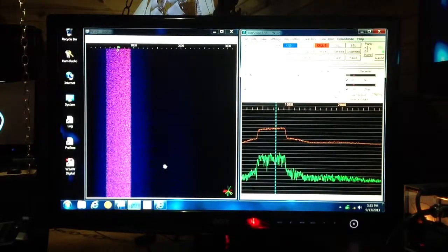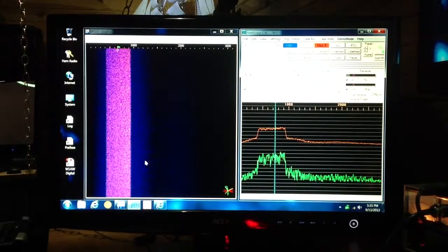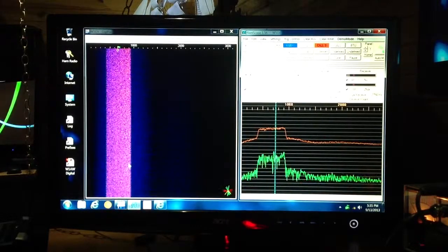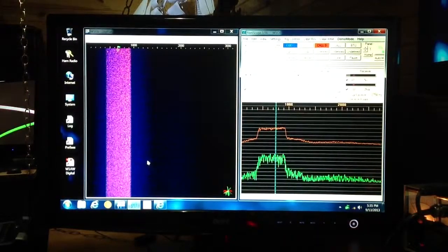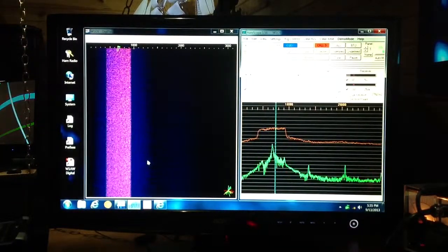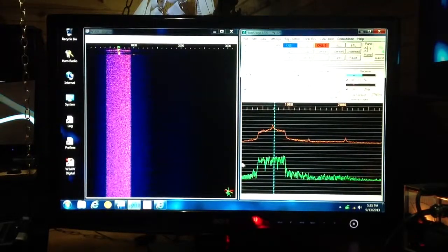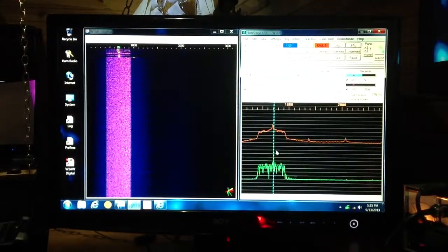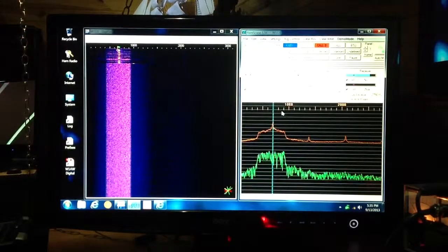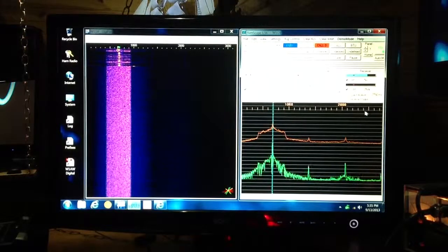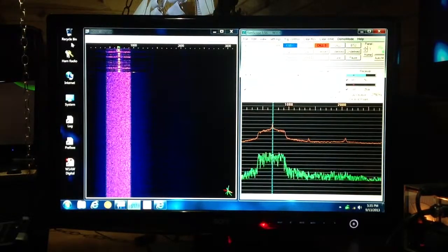What you see here, the lesser levels are black, then blue, and then it turns to violet. And if there was actually a signal coming in, which I can actually arrange for, you can see what that signal looks like. This is a frequency domain display, meaning that the frequency is the independent variable or the domain of the function on the horizontal axis in both cases.